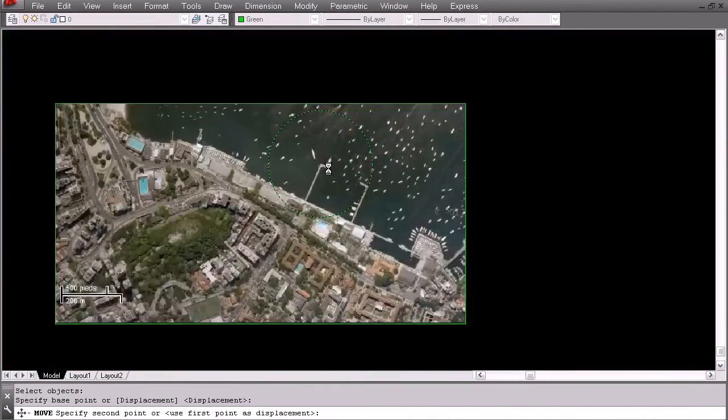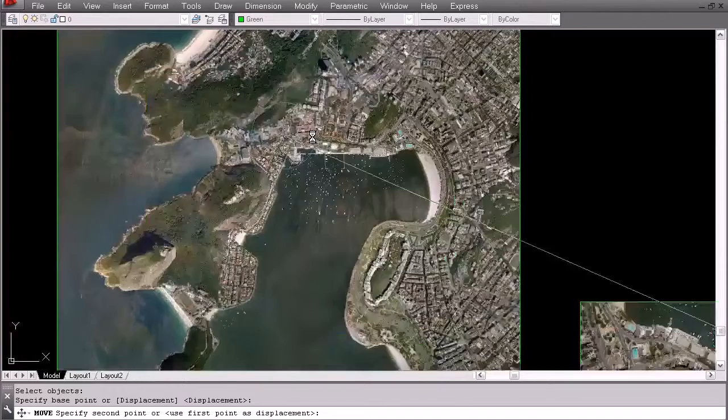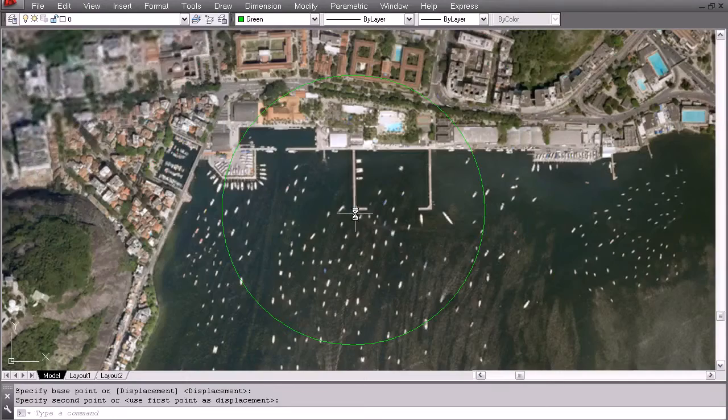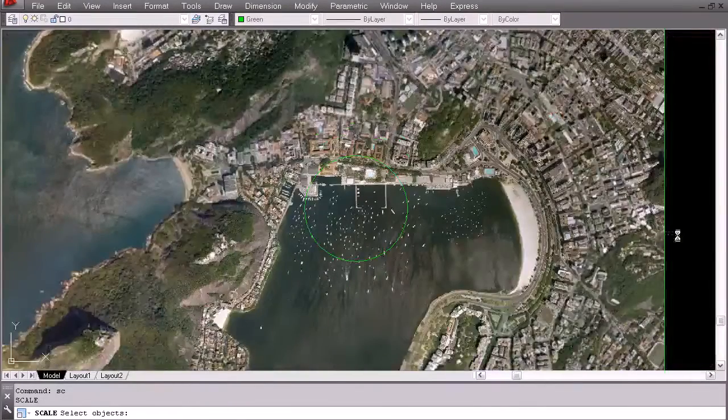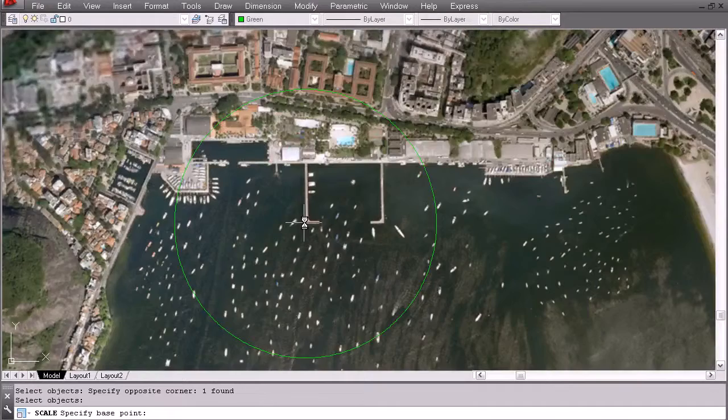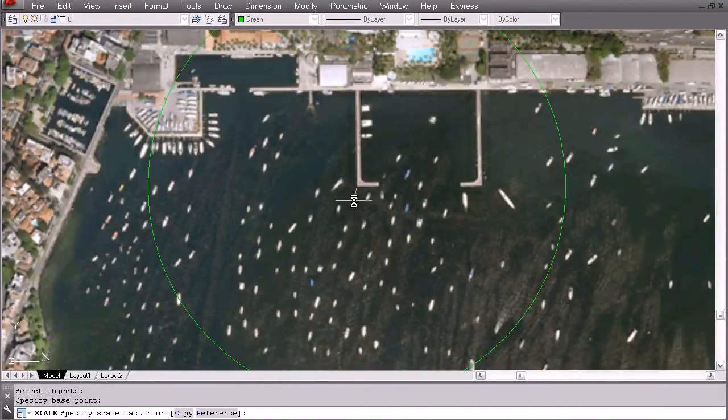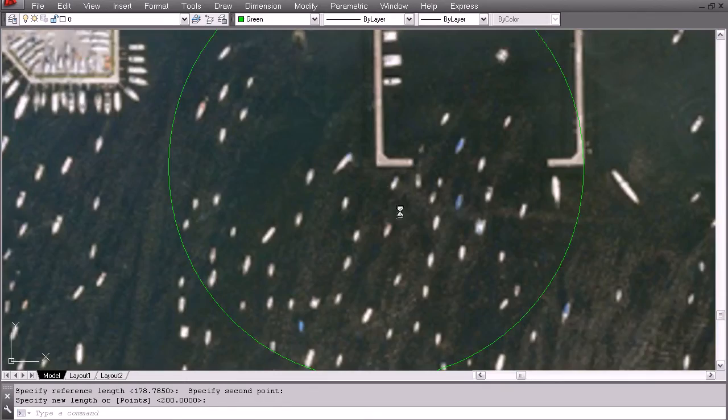Now I'm going to draw a circle between, just to show me the distance from the center of the circle to the edge. Now you can use lines or squares or anything you like. I'm going to use a circle just because the rotation is different between the two. Now I'm going to position that circle right here on that corner. Again, I know this is not 100% accurate. And using the scale tool, I will scale from the middle of the circle, snap onto it, using that reference. And I'll grab this corner here, and I will just scale it to be there.